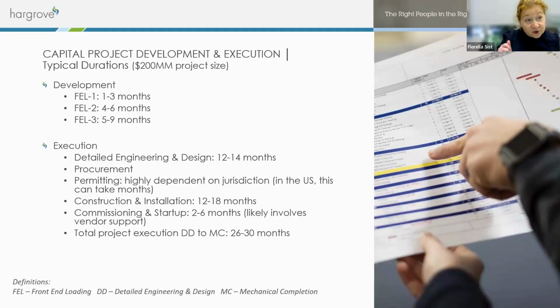Now that gives you your plus or minus 30% TIC, total installed cost, and you start to formulate a clear idea of what the plant is going to look like, exactly what pieces of equipment you need to buy, and you're making decisions of final designs, right? Of what path you're going to take.